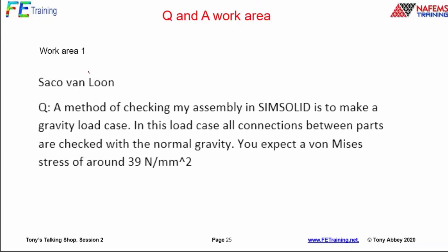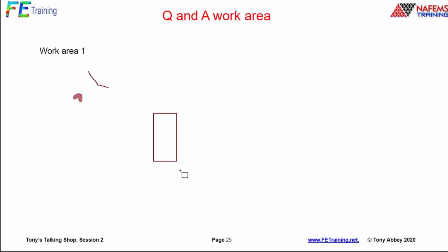If you do a body load analysis, then it's very useful because every element has a volume, a density, a mass. So we get little distributed forces throughout the structure. My explanation there is that every part of the structure sees an internal loading. Otherwise, if you have a structure connected to ground, and you come in and load, say, in here, then there's really zero stress up in this region.